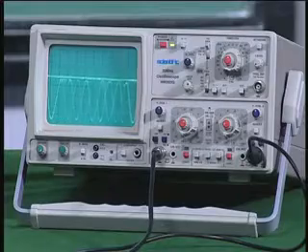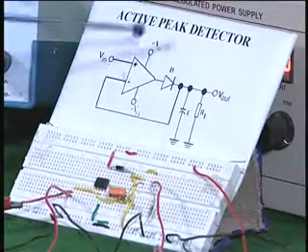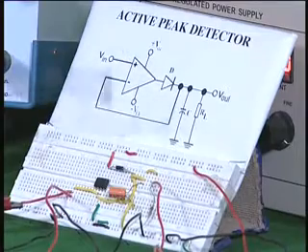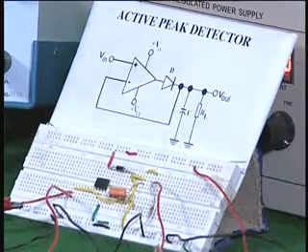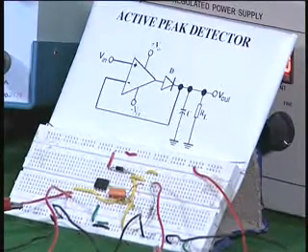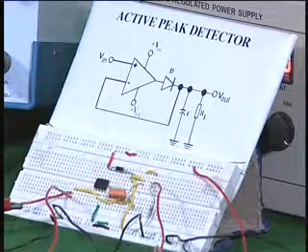So, with a very simple op amp, diode and a capacitor, we are able to make a peak detector, and once I make a peak detector I can connect it to a multimeter or whatever and calibrate it in terms of either RMS or peak voltage. So, we have seen 3 different circuits so far. One is a basic precision diode or rectifier, a half wave rectifier, and then we also saw a full wave rectifier, how a half wave rectifier along with a summing amplifier can be constructed to give a full wave rectifier. We also saw a peak detector by using a capacitor at the output.